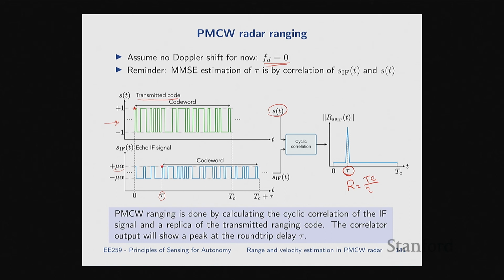Now, as I said, today it's not as widely deployed as FMCW. Actually, you cannot go and buy an off-the-shelf, fully integrated PMCW transceiver, which is kind of sad because, in my mind, from an architecture and DSP point of view, it's a more interesting, more capable technology. I hope we'll see more of it.